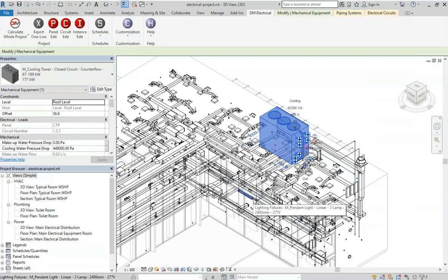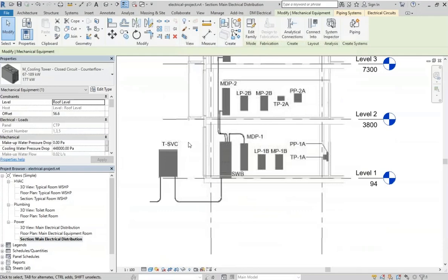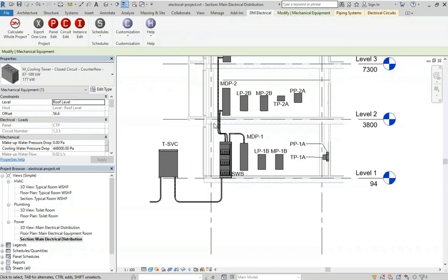Those are the settings we have for branch circuit devices. We can also make changes to distribution equipment, so let me pull up my distribution equipment plan here. Again, distribution equipment are panels, transformers, anything that connects to something else that has something downstream of it being powered, that has other things connected to it. That is generically how we think of distribution equipment.